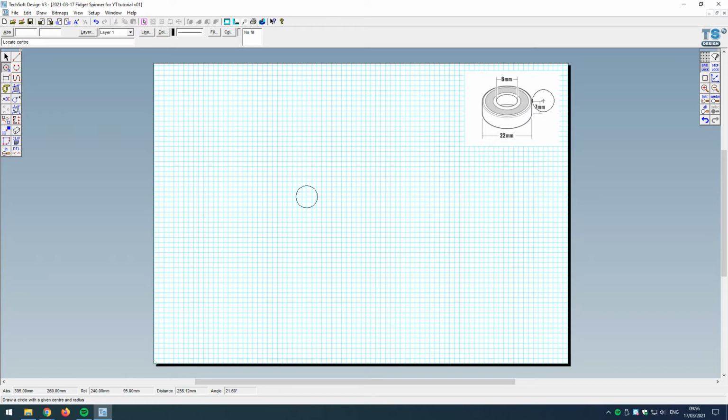Okay, actually looking at the size of the bearing here, I can see it's got a thickness or depth of 7 millimeters. So actually, rather than plywood, I'm thinking a thicker material, because plywood normally comes in like 3.5, 4mm thickness. This could be done in 6mm thick MDF, or actually I think acrylic might be better. And we could do it, for example, in 5mm thick acrylic. That could be really cool.